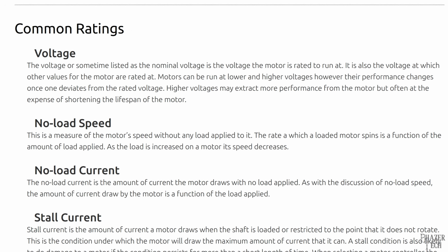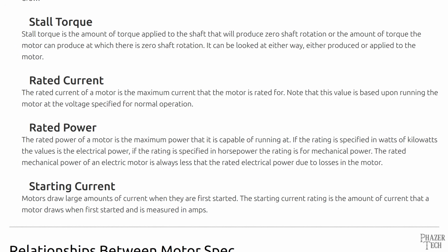However, doing this will likely cause the motor to overheat and fail, so it's not recommended to do this. Likewise, if you apply a voltage that's too small, then there's a chance that the motor won't turn at all. So there's generally a minimum voltage required to get it moving. Now, depending on how much voltage you apply to the motor, its required current will also change. The higher the voltage, the more current the motor will need, and you'll need to make sure that both your power supply and the driver circuit can supply enough current.